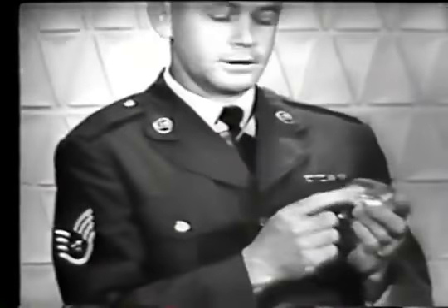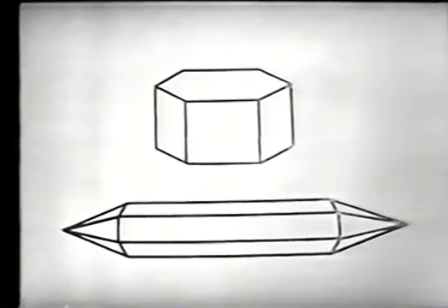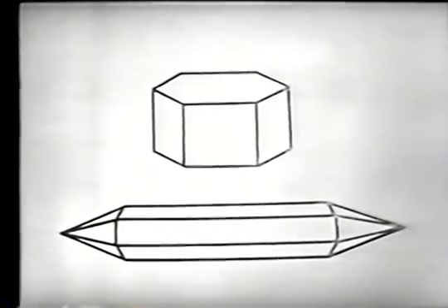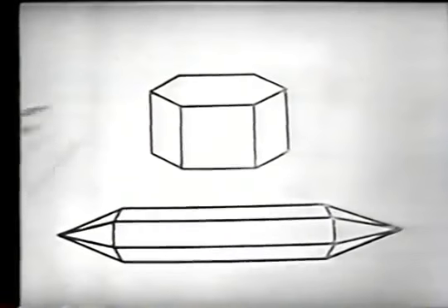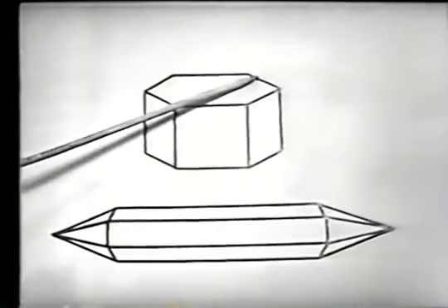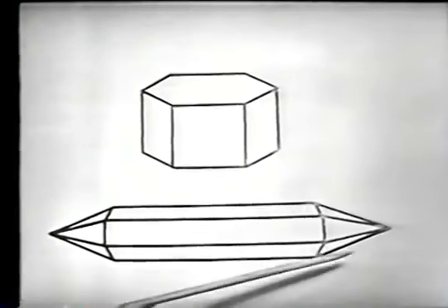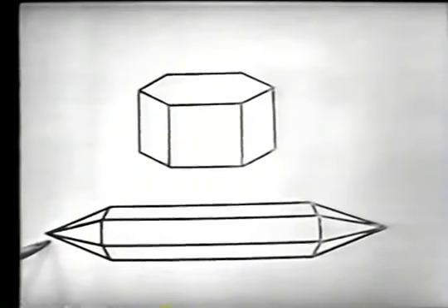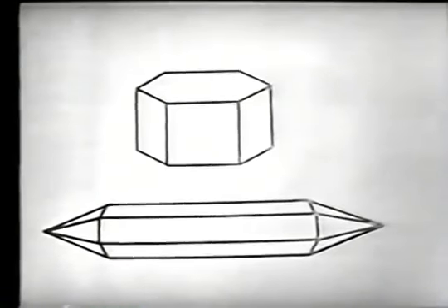Now let's take a look at this drawing so that we can determine more about the quartz crystal. There are two views. The top view indeed shows us that the quartz crystal has a hexagon shape, 6 sides, while the lower view points out that indeed the quartz crystal in its natural form does have pointed ends. Quartz crystal in its natural form cannot possibly be used in oscillator circuits. It must be cut in a specific manner to exhibit its piezoelectric properties.